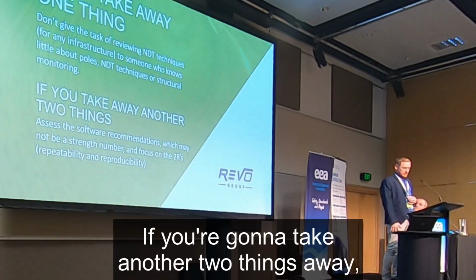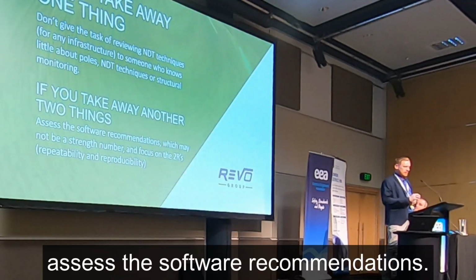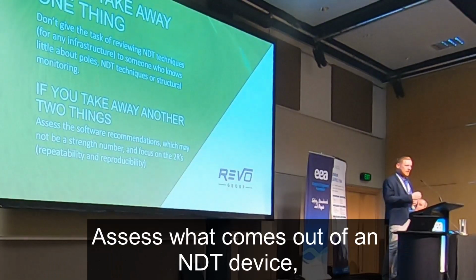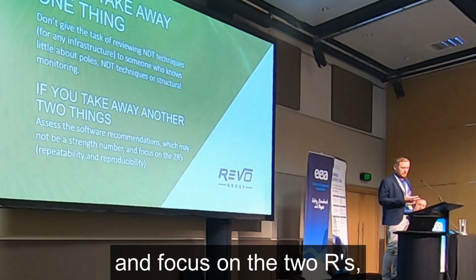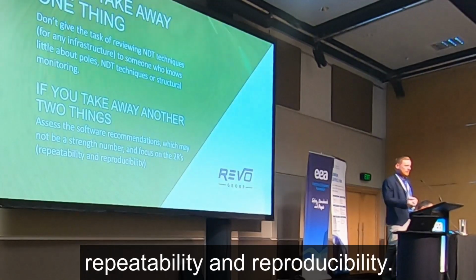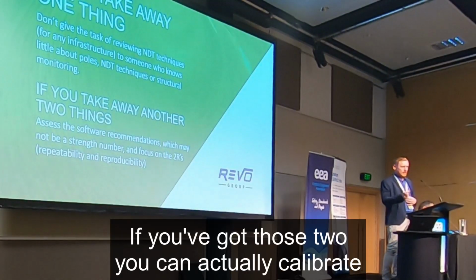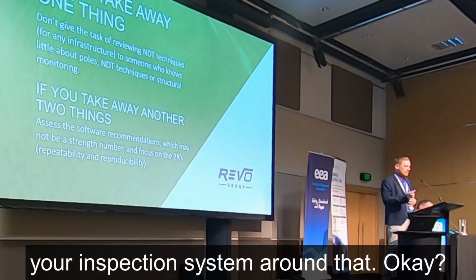If you're going to take another two things away, assess the software recommendations, assess what comes out of that NDT device, and focus on the two R's, repeatability and reproducibility. If you've got those two, you can actually calibrate your inspection system around that. Okay?